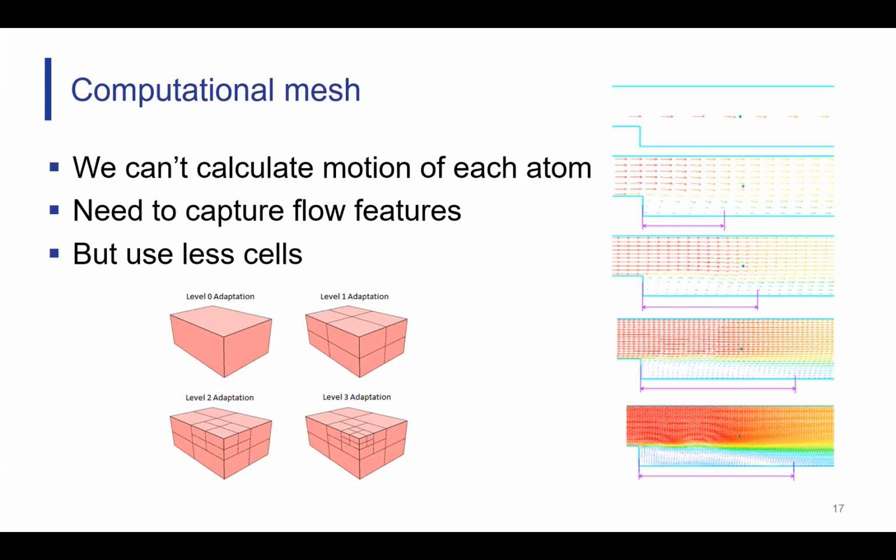In the CFD world, time is money. Literally, time is money. I know it's a phrase, but here it really does apply. Why? Because you have processing power. If you're renting servers, server rent time, project time, and we can be talking a difference of days and maybe even weeks here. So you want to capture the flow as accurately as possible while using the least amount of cells possible. And of course, nothing is ever ideal. So you're going to be looking for a balance between the two.